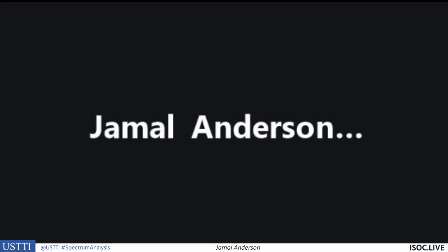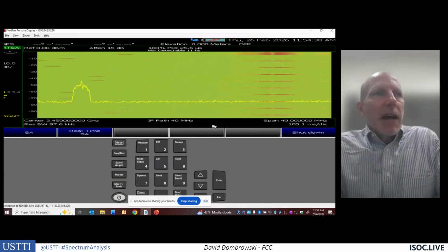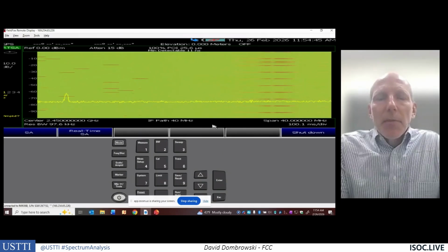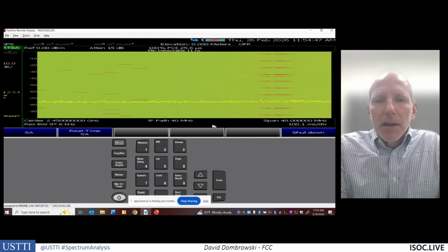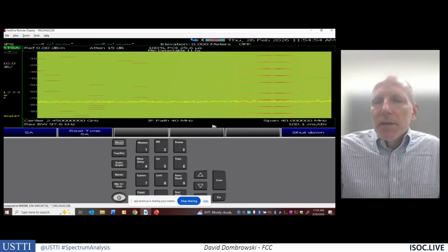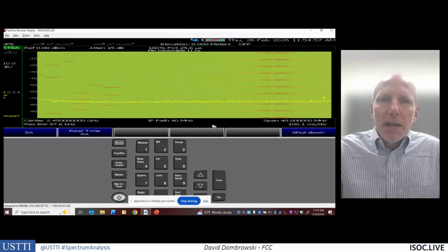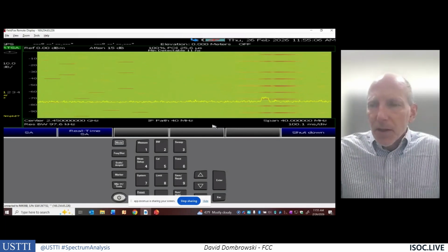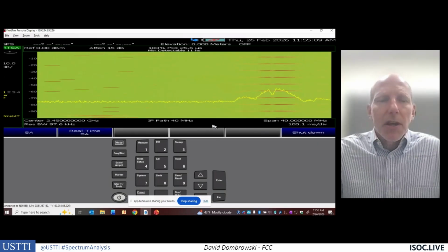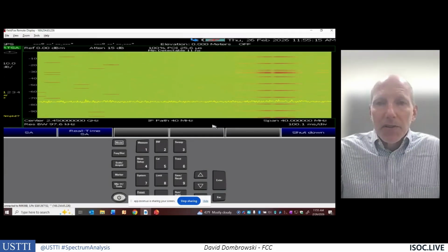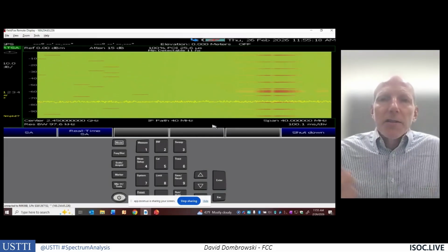And what's the average noise for the LTE band? The average noise, how they design it here in the United States, they try to design it at the base station to be about minus 105 dBm. We've had debates with some of the cellular providers because, especially in urban environments where it's very noisy, it's hard to keep that minus 105 dBm noise floor. And sometimes that's difficult when you're in an urban setting with other transmitters, all those radiation sources such as LED signs, equipment inside buildings, computer equipment. It just increases the noise floor.